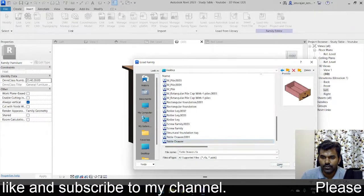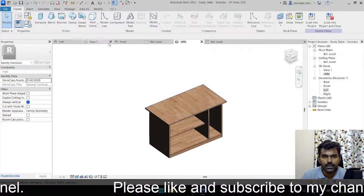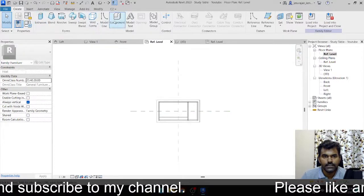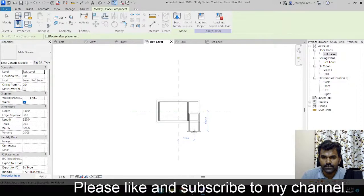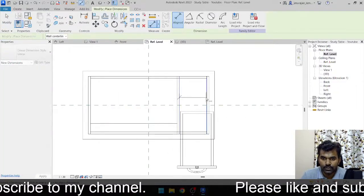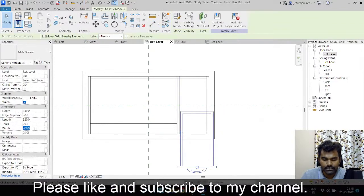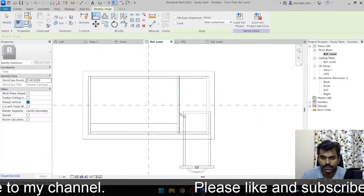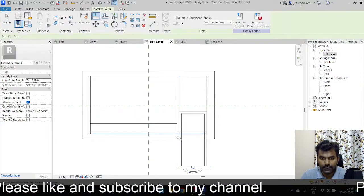Table drawer, open. Okay, go to create and go to reference level, go to create component, and you can see you can just place this here. What's this size? 250. Select and keep the width as 250. Okay, and just add it here. Align.